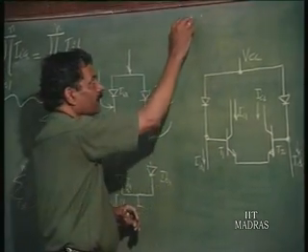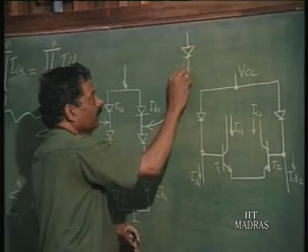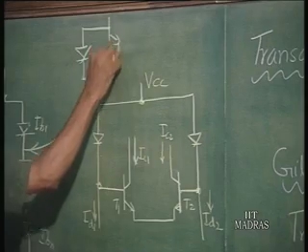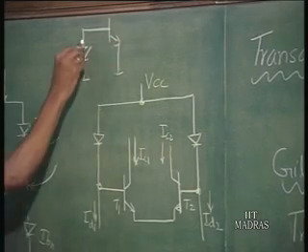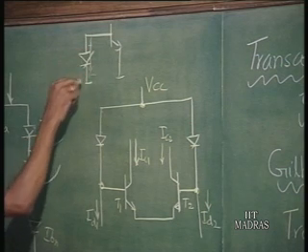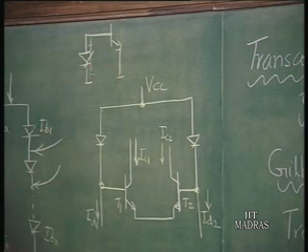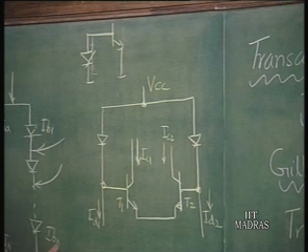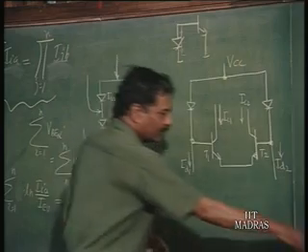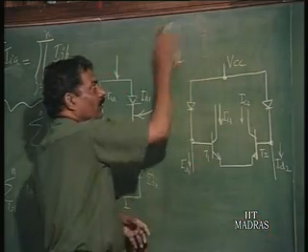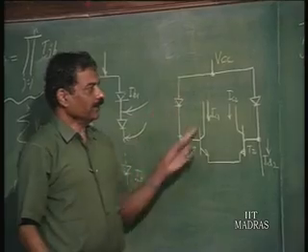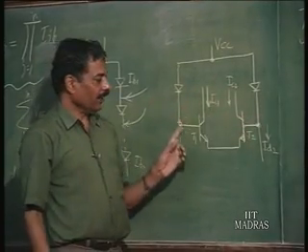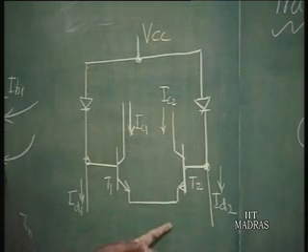A current mirror is the first example. For example, one diode with another junction. So, this current in this should be same as this current, that is single diode. So, that is the basic principle of translinear, applied to a pair like this. Now, here this is slightly more complicated. You have two diodes and two junction transistors connected in a loop.